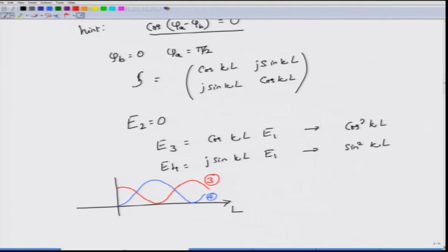You can now determine whatever value of L that you want in order to give a certain fraction of the output power. Suppose I want to send most of the power into the third port, then I will choose my length to be equal to some L1. Let us also suppose that this power fraction should be about 95%, that is to say, port 3 gathers 95% of the input power, whereas port 4 then must gather only 5% of the input power. What is the value of L1 required in order to do that?